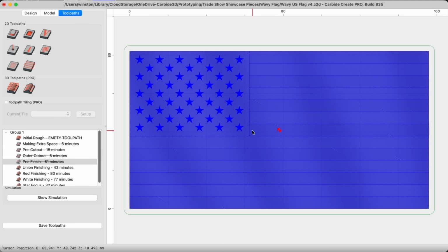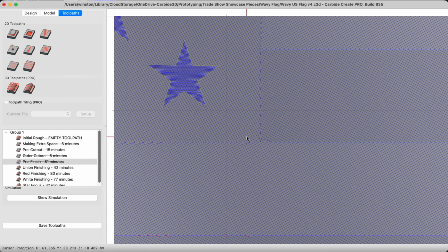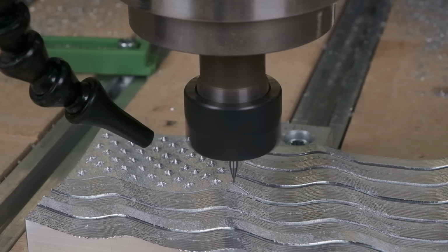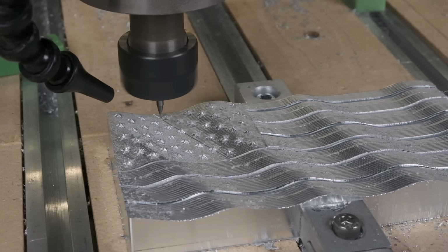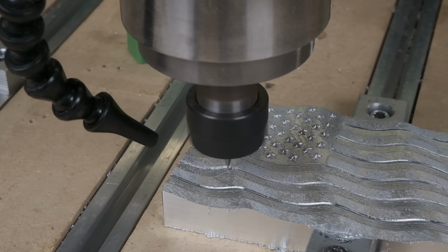And one last variation I'll just throw out there is that some materials, like aluminum, tend to show tooling marks pretty openly. But if you take an artistic approach to how you do your tool pathing, this can actually be an advantage. Here I'm applying my finishing toolpath with different directions and even stepovers to create additional visual contrast between the stripes, the union, and the stars.